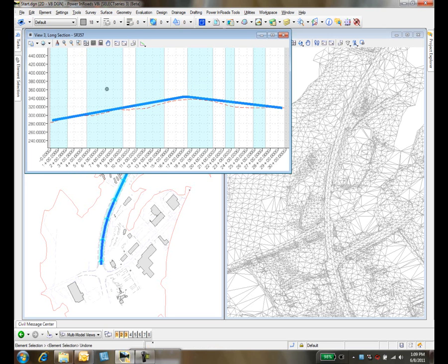Now again, we can come in here and design multiple profiles, alternate ones, alternate two, but at some point before we begin to move ahead with our model, we want to have the ability to set an active profile. So what I'm going to do is hover over this, select this proposed profile and hover, and again when I do I get my context toolbars. Now you'll notice that I don't get a best fit option. Even though this is a profile, the context toolbar actually recognizes the difference between an existing and a proposed profile and can dynamically give you updates and changes on the fly.